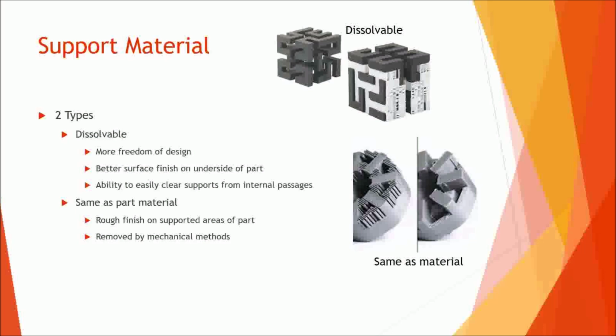On the other side, we have supports that are the same material as the part, and this limits your design freedom, because you have to actually remove these with a pair of needle nose pliers or a dental pick. It's very time consuming, and it can be very difficult, especially if you have small internal passages or confined spaces. It can be almost impossible to get that support out. So that's where you have the big benefit of dissolvable supports.